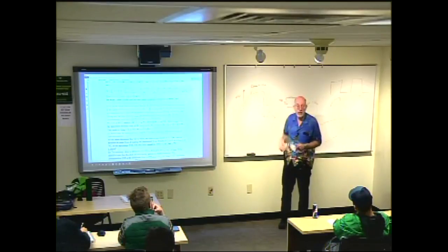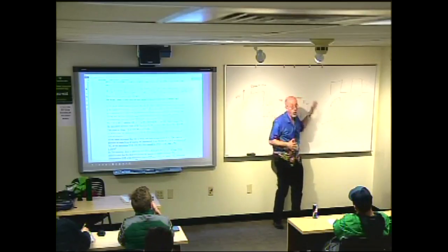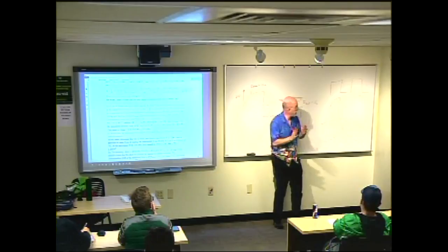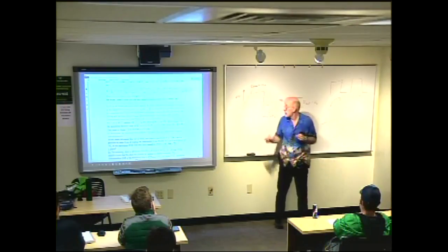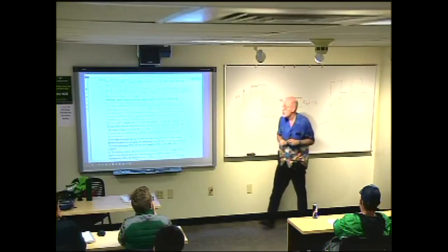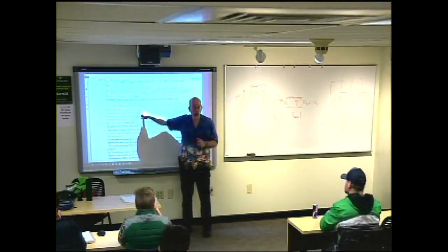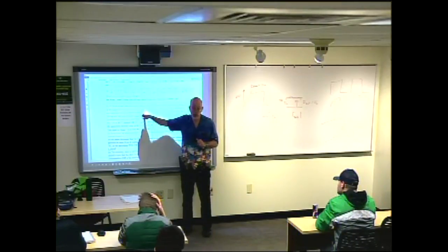So if I want to make sure that my filter handles both edges, the one that's going to be more of a limit in terms of how small I can make the bandwidth of this filter is going to be the faster one. So when I do this calculation here, I want to use tau is 2 seconds instead of using tau is 10 seconds.